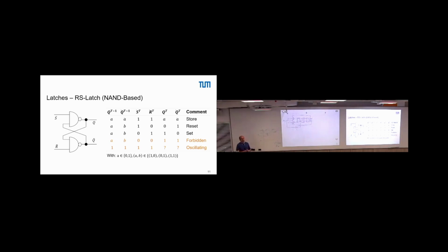Then we have a second part. If the clock edge comes, that effectively sends the data out from the internal node, namely the clock edge which disables this latch and enables this latch. Yeah? Then it first takes some time until we propagate out, which we call propagation time. Yeah? So we have some delay of the flip-flop added, effectively from here to here, which is effectively the propagation delay. Yeah?